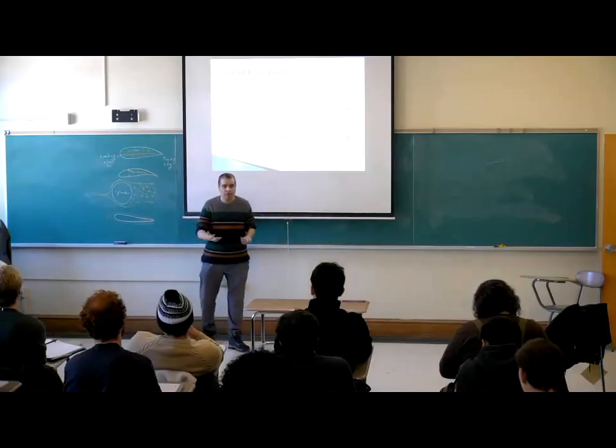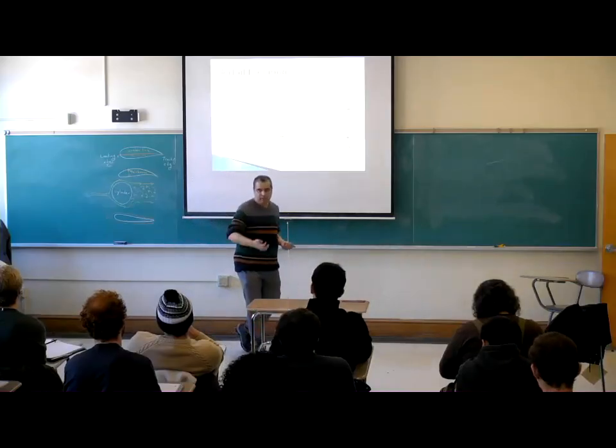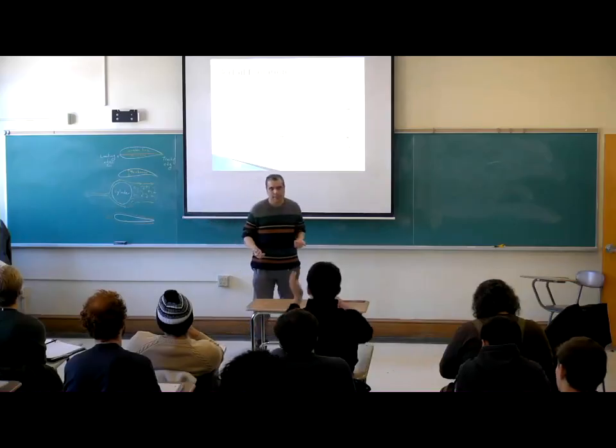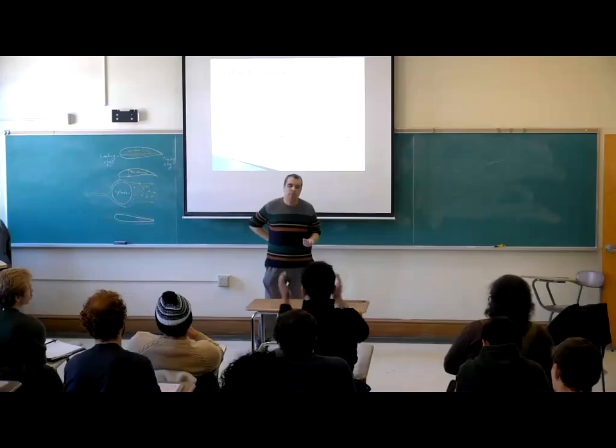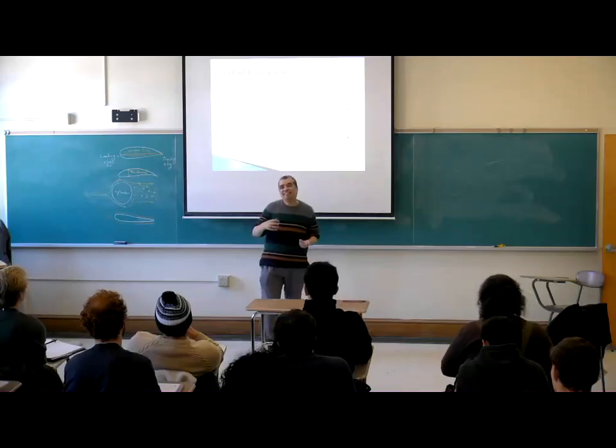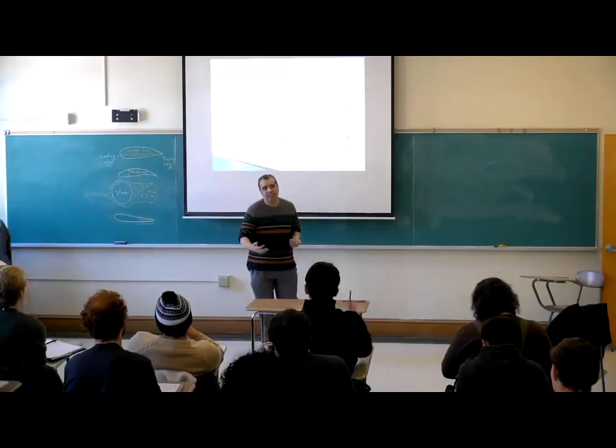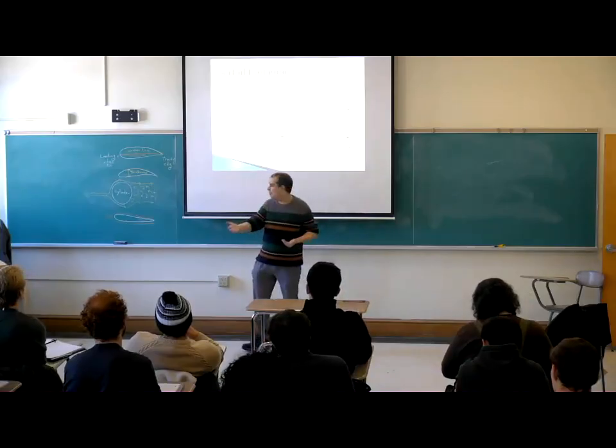Can anyone tell why? Yeah? Well, in terms of the airfoil, if it's at maximum angle of attack, that dead region acts as something that has to move with the airfoil, so that leads to stalling. What else do they increase? It increases drag. Drag force, yeah. They increase the drag force.